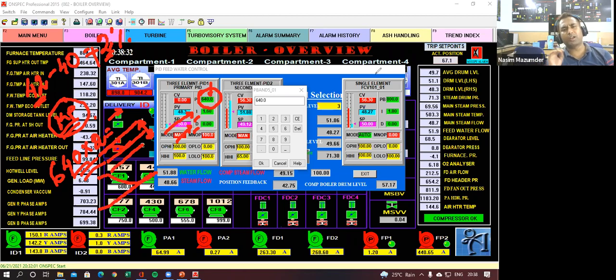And you have to note it down every time. Once it is set, you note it down, and you ask the operators to observe the response of this control valve. After 1 day, you collect the feedback, okay, these are the variations. You can go through the curves and then once again change your settings. So this is purely trial and error. Okay.